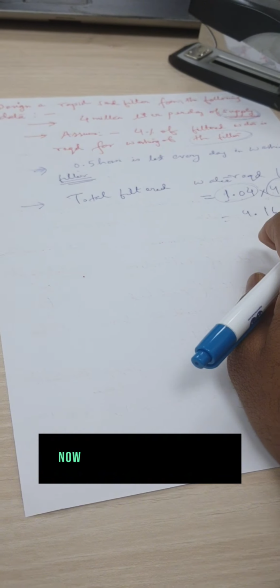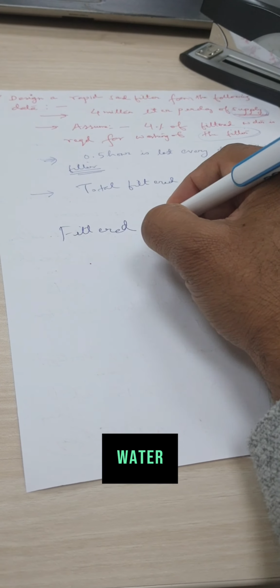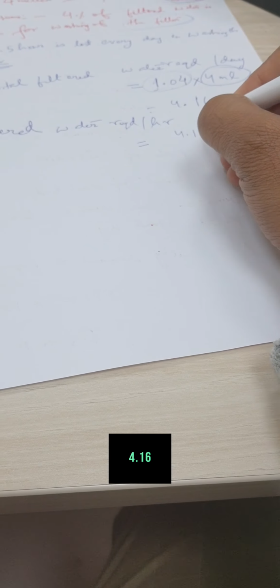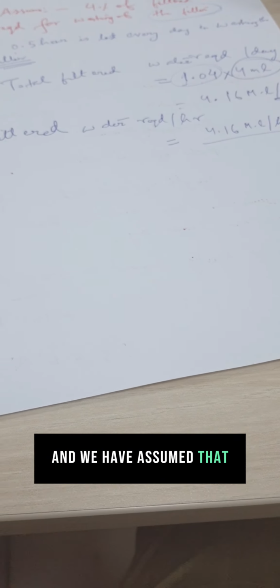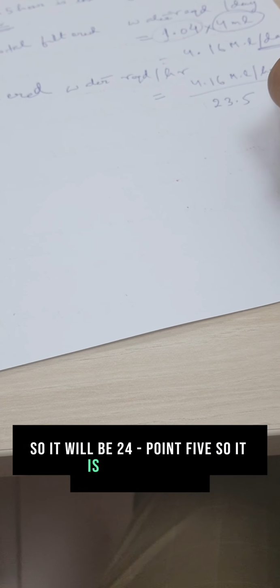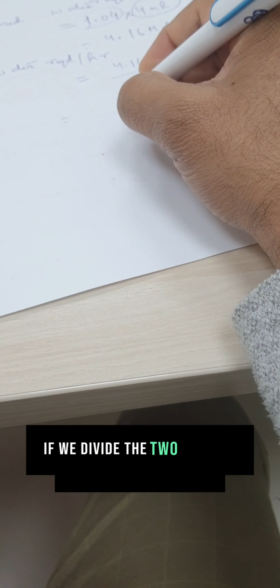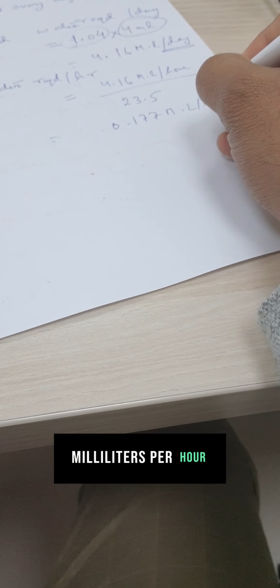Now the filtered water required per hour is 4.16 million liters divided by the hours of operation. We have assumed that the filter is operating for 24 hours and half an hour is lost, so it will be 24 minus 0.5, which is 23.5. If we divide the two terms, it will be 0.177 million liters per hour.